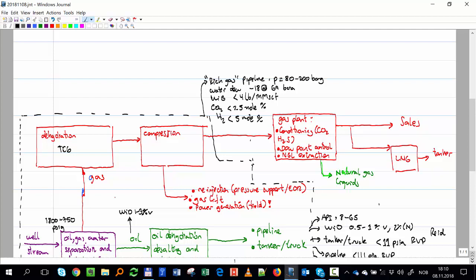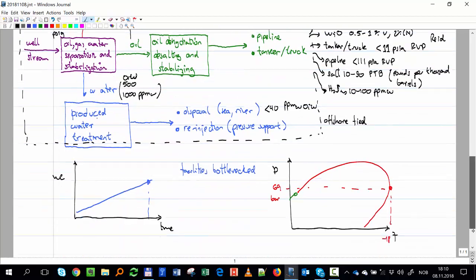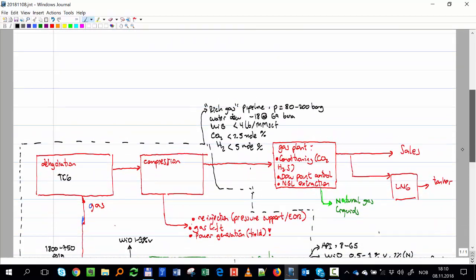And then we have two other criteria related to the envelope of the gas, and they say that the cricondentherm should be located below, I think there is a mistake here. It says 40. Yeah, 40. I have to check this number, okay? But the cricondenbar has to be less than 105 bar.